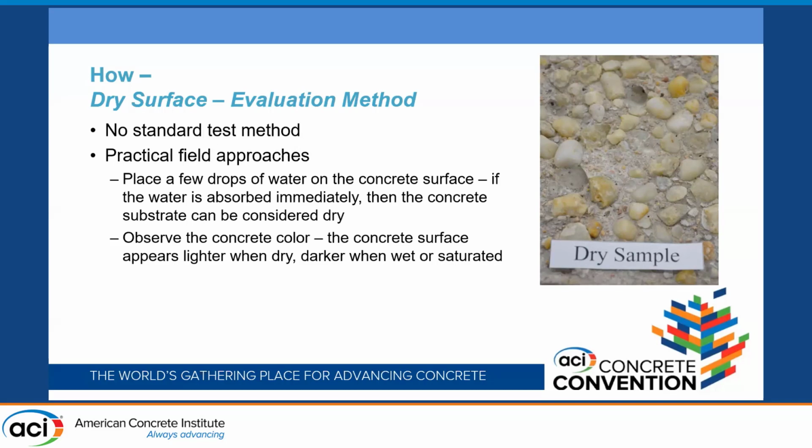How to evaluate if the surface is dry enough? There's no standard test method available in ASTM or other documents. The practical field approach recommended by the committee members includes, for example, placing a couple of drops of water on the concrete surface. If the water is absorbed very quickly, disappearing, then the substrate can be considered dry. The other way to look at it qualitatively is to observe the concrete color. Commonly, the concrete surface appears lighter when it's dry, but darker when it's wet or saturated.